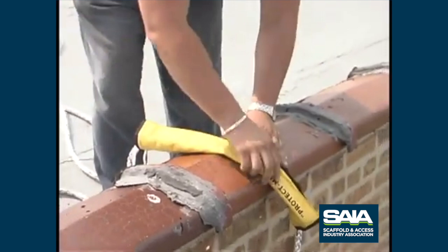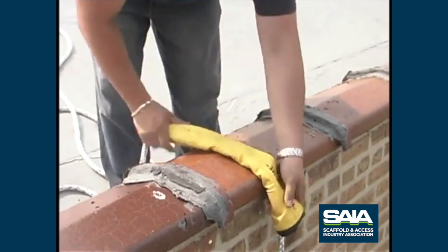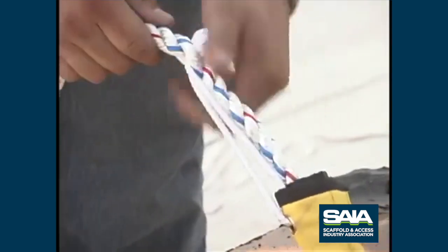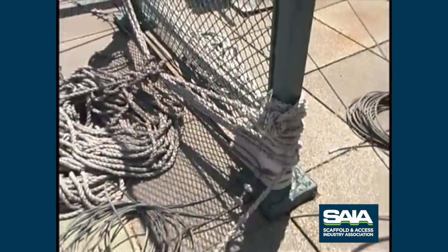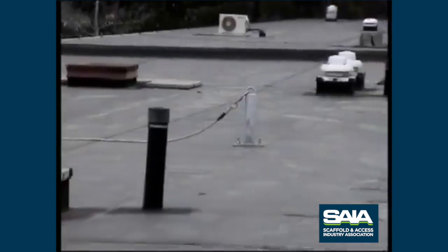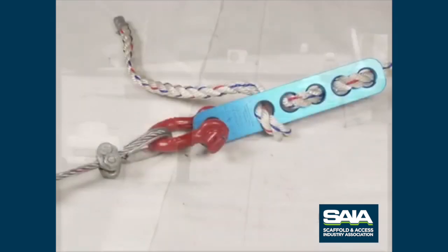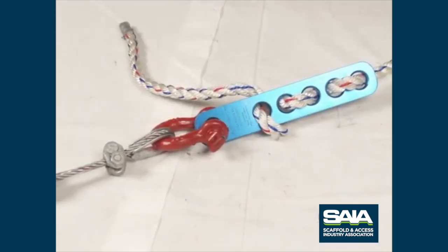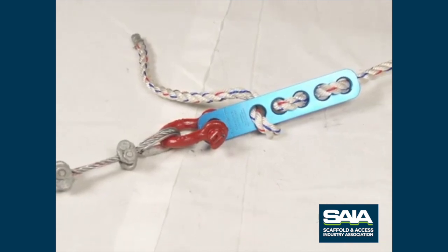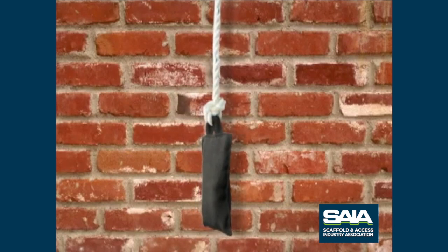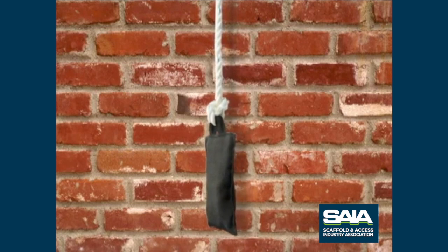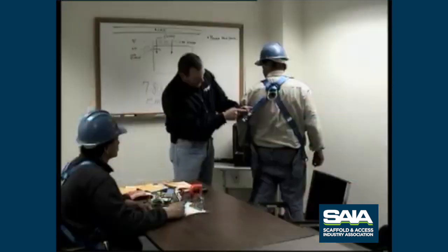Always cushion the lifeline against damage from sharp edges by using a piece of rubber hose, wooden buffer, or other protection. Be sure the protection devices are secured against movement. Do not use knots to terminate lifeline or synthetic rope. Secure the lifeline to an independent anchorage on the structure with a mechanical splice termination plate, or, where allowed by law, an approved knot that retains the required strength of the line. Always check local codes. Lifelines should be secured at the bottom with weights or attached to structures. This keeps the line taut and allows the fall arrestor to move more efficiently.